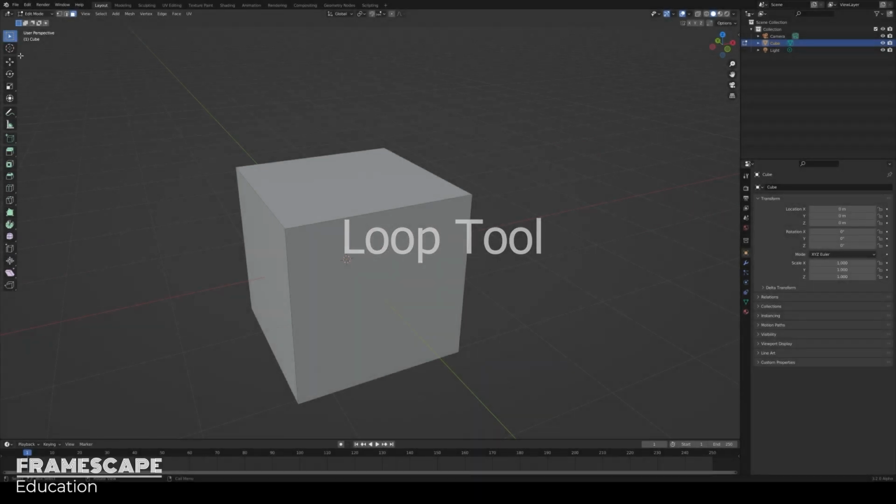When you're in edit mode, there are many tools to expand upon, manipulate, and modify a shape like a cube. The one that we're going to use in our first lesson is the loop cut tool, also known as edge loops. I'm going to click on the loop cut icon and bring my cursor, which is turned into a crosshair, over to the shape. When I hover over the shape, a yellow outline highlights where it's going to cut my shape. And when I click, it adds a cut into the shape.